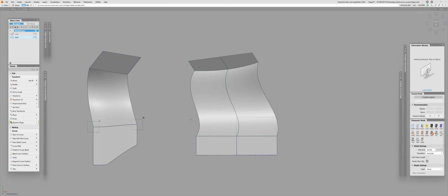Okay, so as a conclusion, let me sum this up quickly: what you should do with the edge align and what you should do with the skew align. With the edge align, if you're aligning to the true edges of the surface, you will not encounter any problems. It will work as it is intended to. If the surface is trimmed, it depends on how it's trimmed. If you cut the adjacent edge to the edge you're aligning, your partial alignments will be distorted, will be deformed. The edges will still follow. If you trim convert the surface, which you trimmed, temporarily, then you will have no problems.